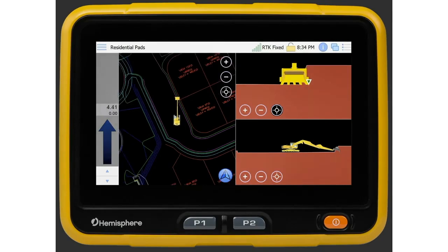Below the left light bar, you will see the up and down arrows. If we click on the down arrow, you will notice that the offset numbers change by 1/10 at a time. The upper number here is showing you how much cut or fill you have, and the lower is our offset. The cross-section view also has a new line going across it that represents our new grade.